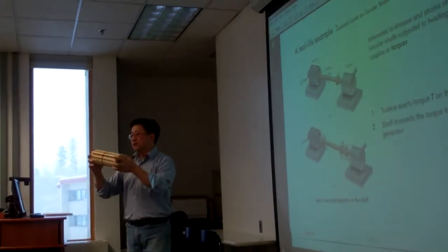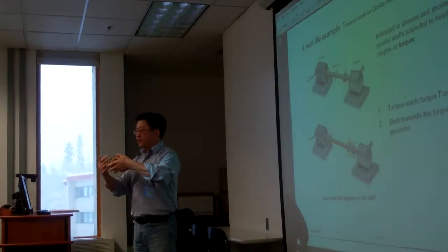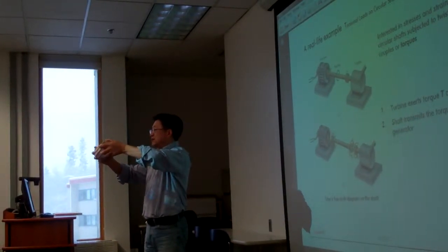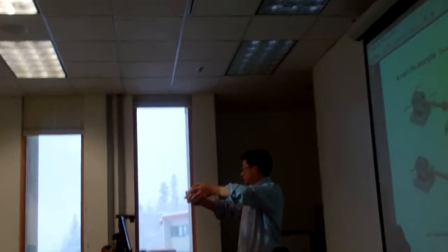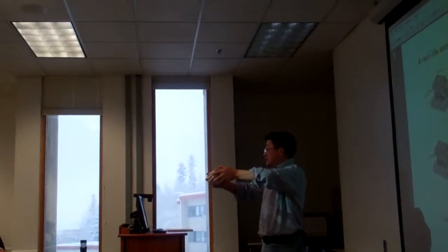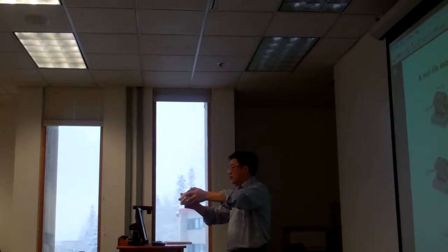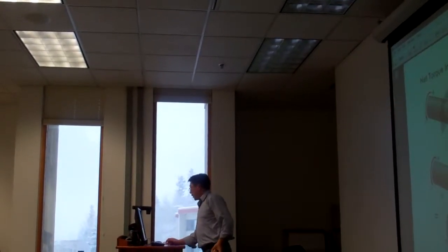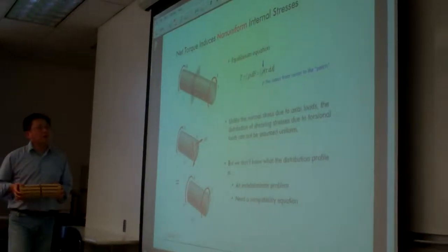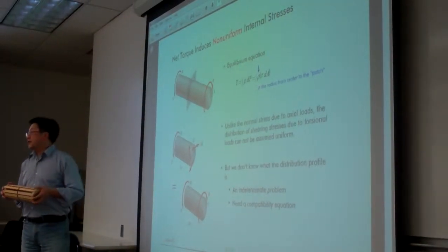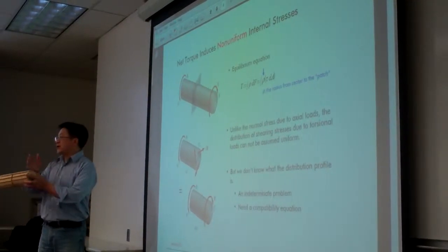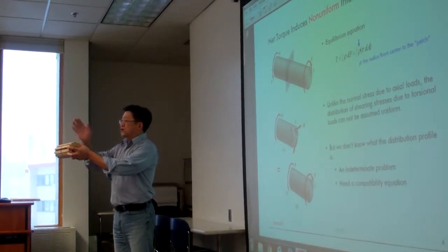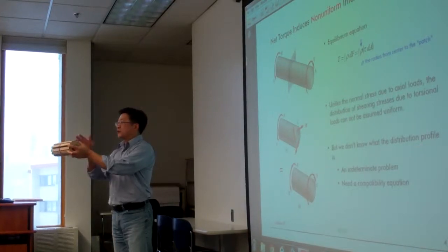If you look carefully, this represents a fiber on the surface of the shaft. When I twist it, the fiber moves a little bit, right? That is the torsion-induced deformation we are going to study in this chapter. That is our model. We start with the fundamental model, which means we assume a uniform shaft. A uniform shaft is one where every cross section has the same area.